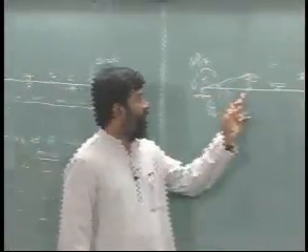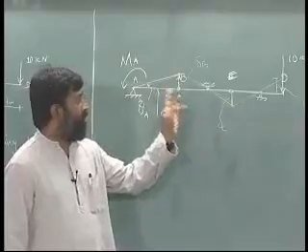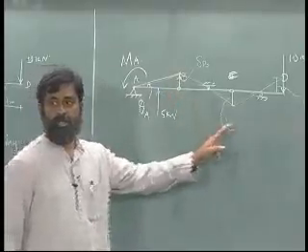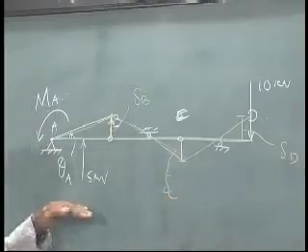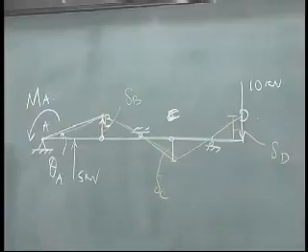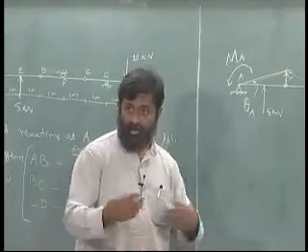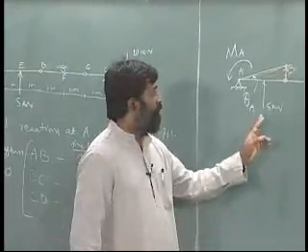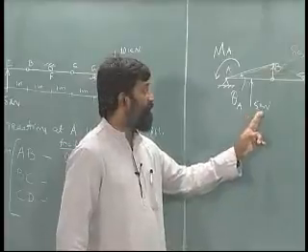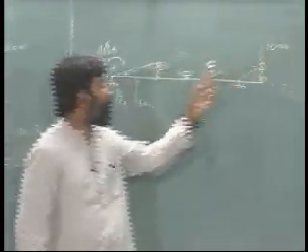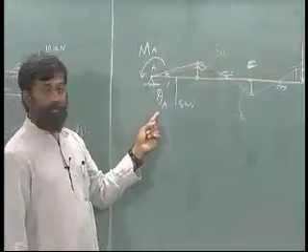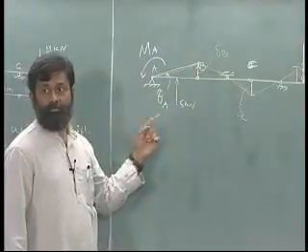Now once I find out delta B, from that I will find out delta C, from that I will find out delta D, okay. So what I am going to do now is find out kinematically admissible virtual displacements, because now we know we have to do that in order to provide the displacements, virtual displacements at 5 kilonewton and 10 kilonewton apart from the virtual rotation that is already given, alright.